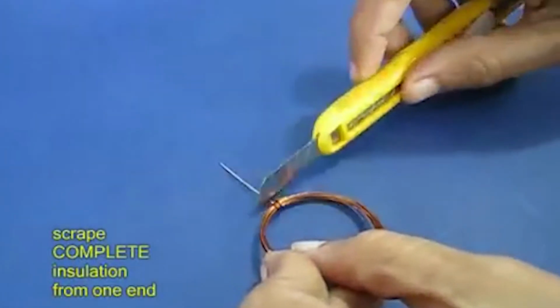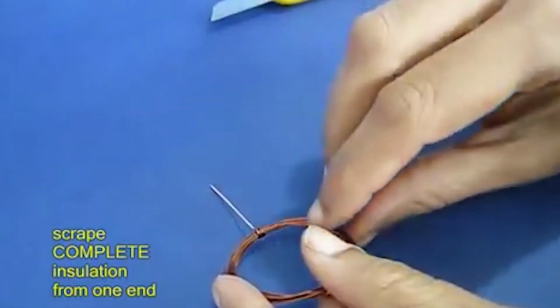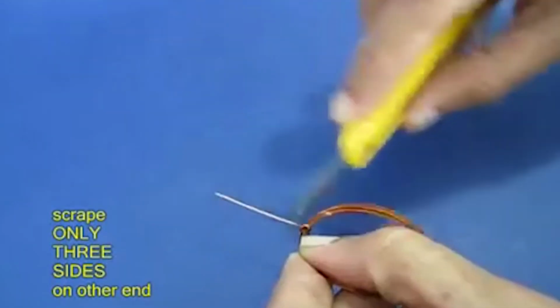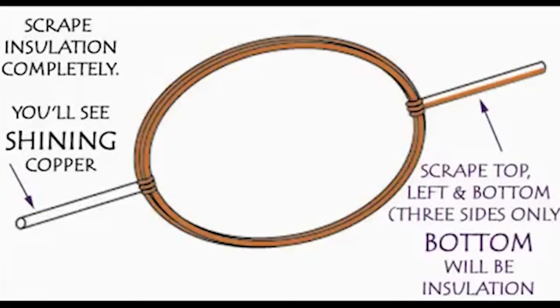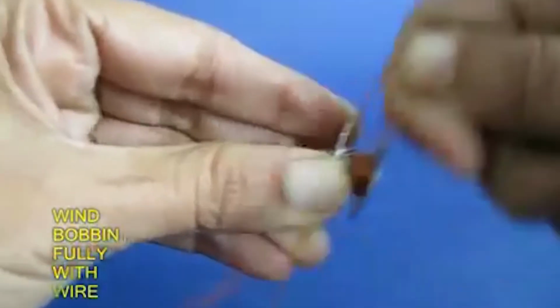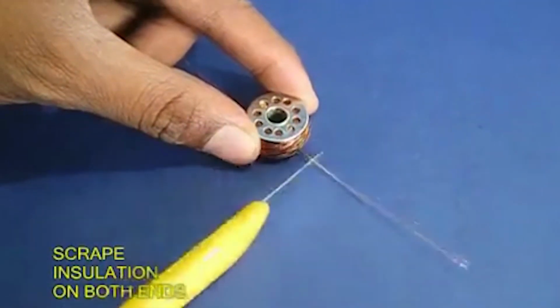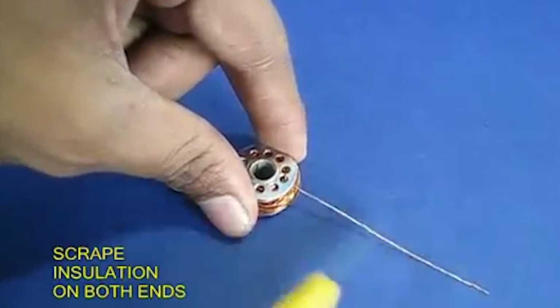Now this wire is insulated, and you scrape the insulation completely from one end. You will see shining copper. On the other side, you just scrape the top, the left and the right, only 3 sides. One side would be totally copper, the other side would be scraped on 3 sides, but one side would be insulation. Then you take a sewing machine bobbin and wind insulated copper wire fully on this bobbin. Scrape both the ends to remove the insulation, and you will see shining copper.